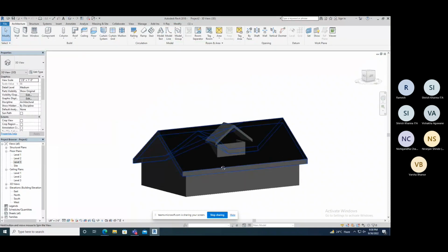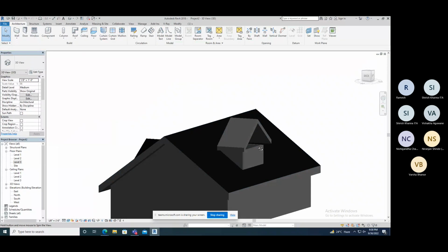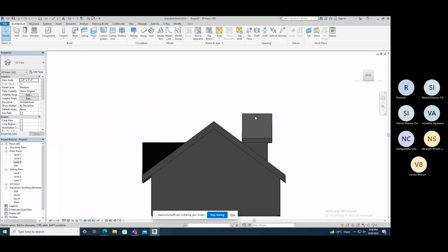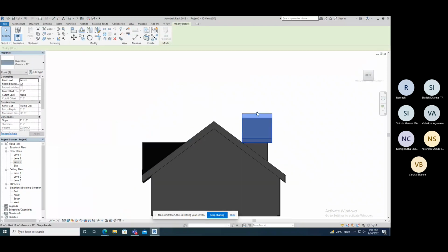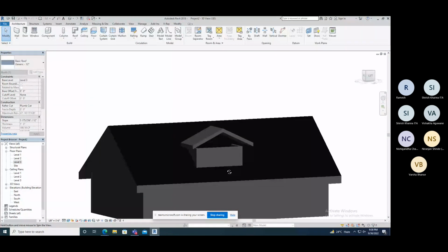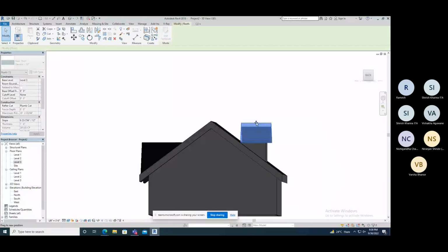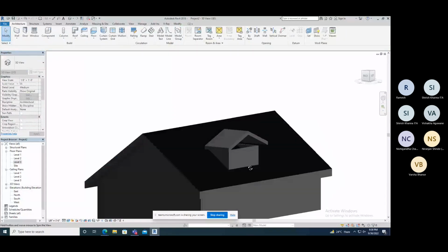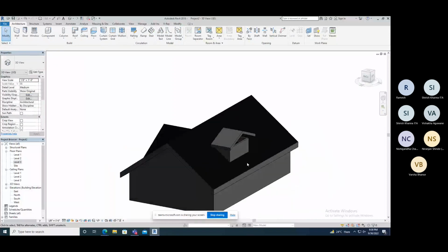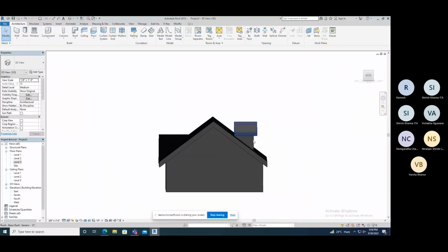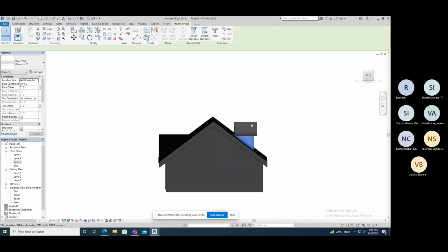Now this is ready. I want to see its height is more, no? So we can reduce its height, but I want to join them also. Okay. Now what do we need to do? We need to select these all three walls first and join with the upper roof. Attach, take a top with top roof. Okay, now see it is attached.